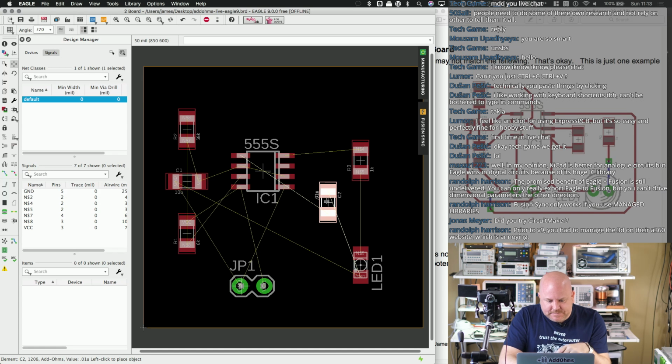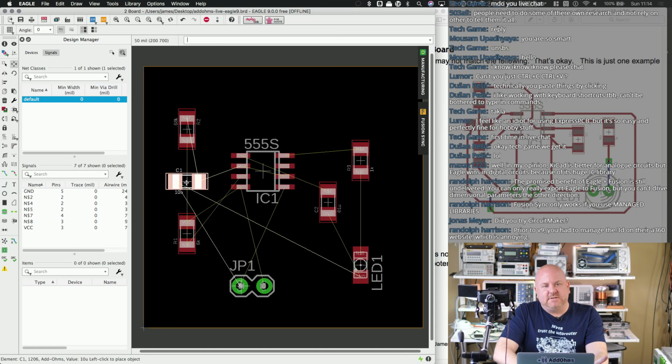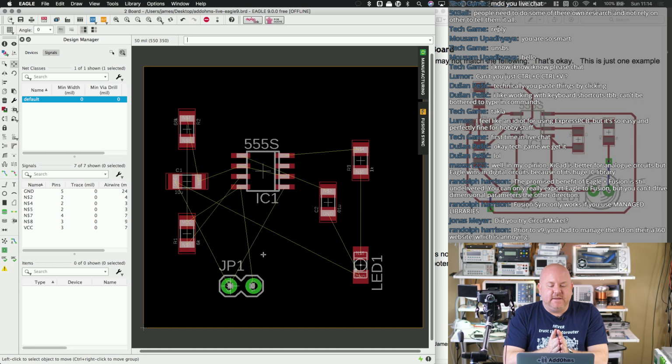Okay, so I need to rotate this one around. Where's this guy? So that should go straight through there. Now, of course, I'm cheating a little bit because I've done this board a lot, so I already know where some of these things should go. One thing, and I said this in my PCB video with the Pyramidino, when you design a PCB, do not hesitate to get about 25% of the way in and then just start over.